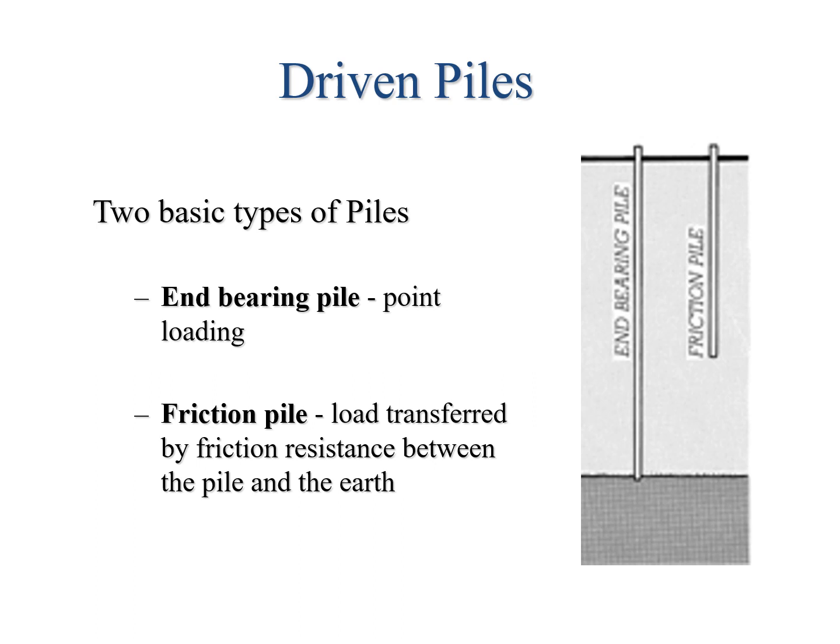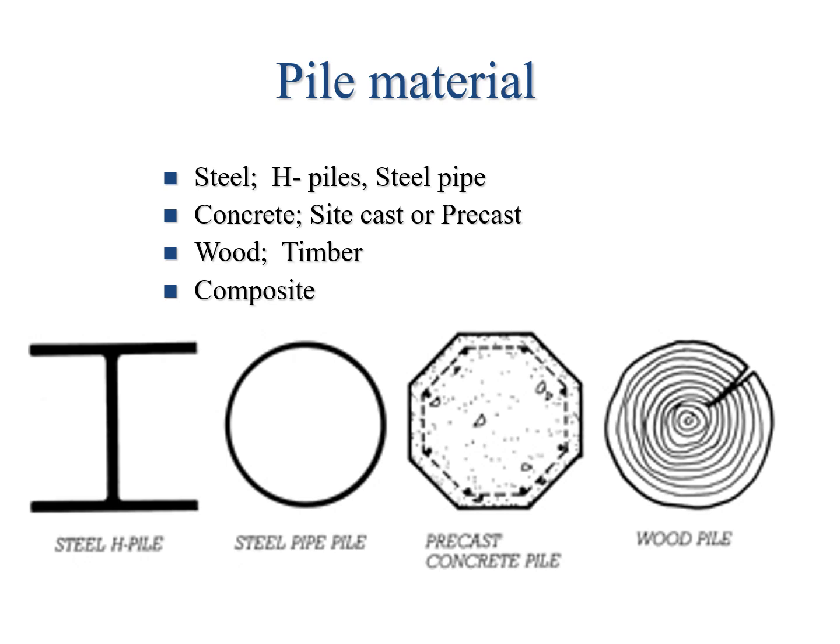Most of the end-bearing pile is doing what they call point loading, and that's just transferring all the weight to that bedrock or rock down below. So here are some of the materials used in piles. Steel, like I said, the I-beam, or the H-pile they call it.